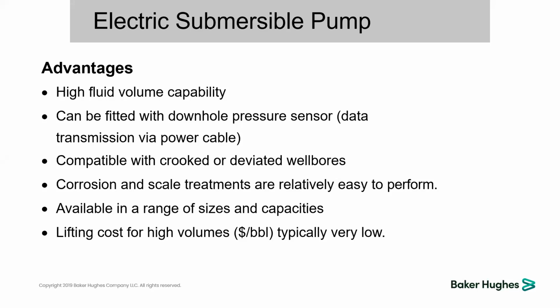It can also be connected with a downhole sensor in order to have real-time monitoring. On the rest of the artificial lift methods, you cannot get the full downhole parameters. On PCP, you can get, for example, only intake pressure. You cannot monitor the temperature. On a sucker rod pump, you have fewer parameters that can be monitored. ESP is a unique artificial lift that can give full parameters to be monitored, making sure you have optimum performance and real-time optimization immediately upon the sensor data.